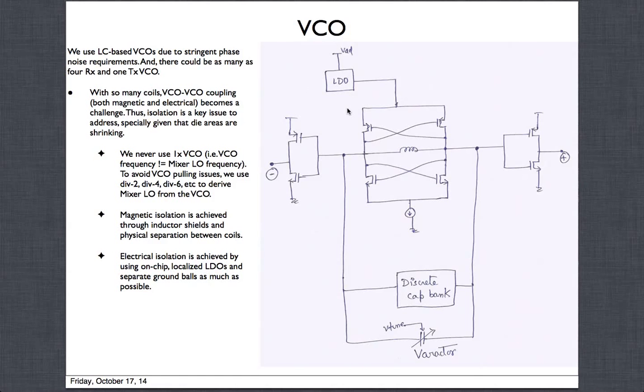They are not going to be at the same frequency, close to each other. When two VCO frequencies are close to each other, they're going to pull each other really hard. One will try to knock the other one really hard. But if they're far away, then one cannot knock the other so hard, because these VCOs have very high gain at a very narrow band of frequency, right? This is an LC circuit, an extremely high Q LC circuit, which will have high gain only at that resonant frequency. But if you go far away, the gain goes down. So it becomes less sensitive to far away frequencies, and only more sensitive to frequencies which are very, very close to the oscillation frequency.